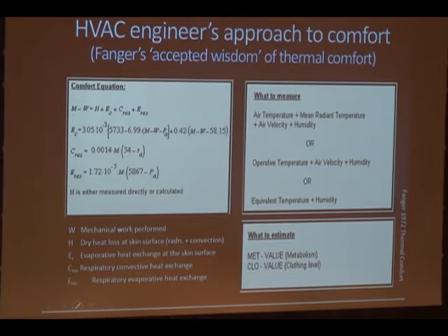And Fanger ingeniously solved the heat balance equation for the human body by overlaying empirically derived comfort temperatures at different metabolic rates, and also overlaying the skin temperature that corresponded with thermal comfort at these different metabolic rates, but also the amount of evaporative heat loss at different metabolic rates.